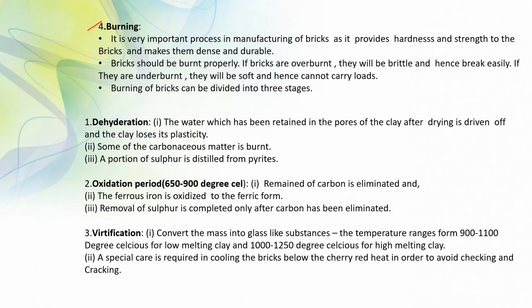Next, what is burning? It is a very important process in manufacturing of bricks as it provides hardness and strength to the brick and makes them dense and durable. Next, bricks should be burned properly. If bricks are overburned, they will be brittle and hence break easily. If they are underburned, they will be soft and hence cannot carry loads.